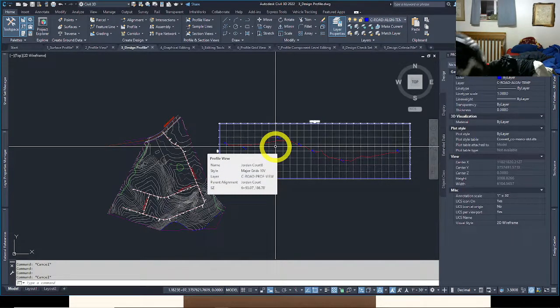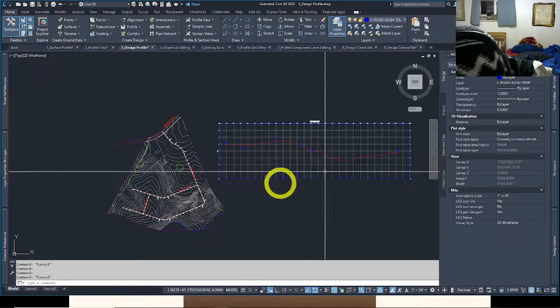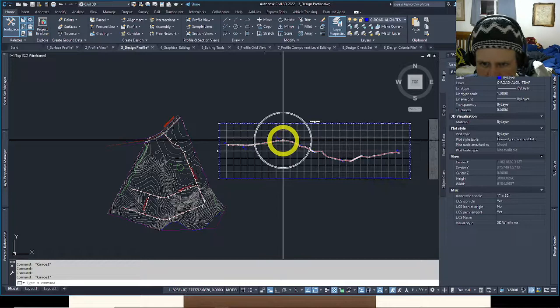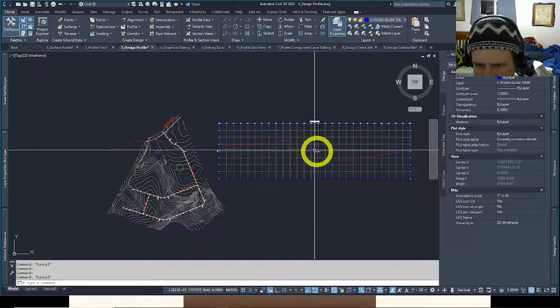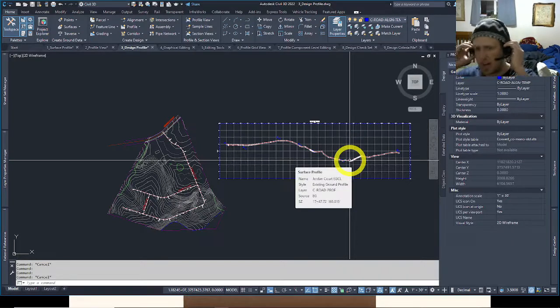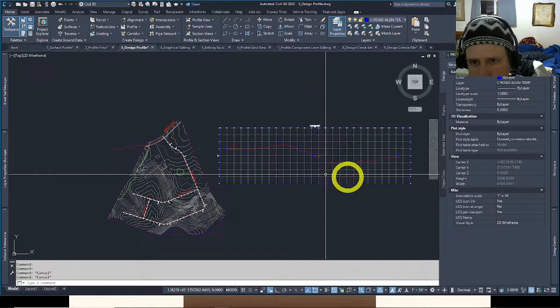So this, as the surface profile shows, we look at the current path. It might not be suitable for driving. Maybe this is too much of a steepness here. Maybe this goes down 10% an average grade. We'll find out when we do a design profile. That would be, you know, most urban roads too steep, not safe enough, not desirable for most design standards.